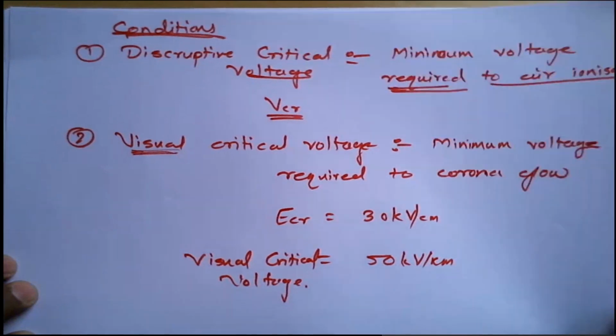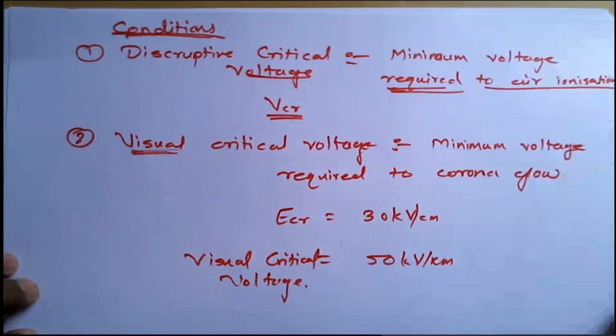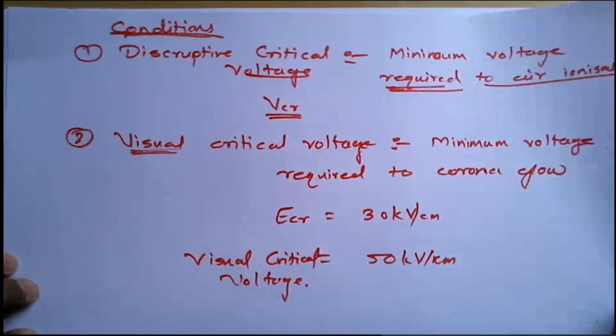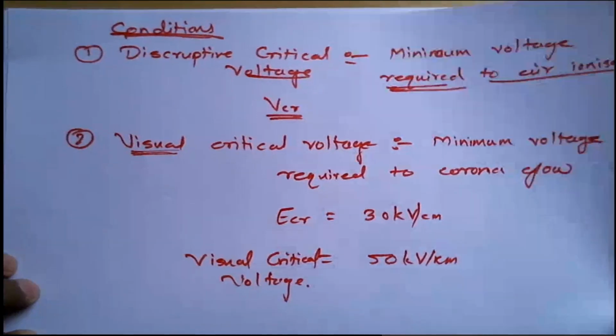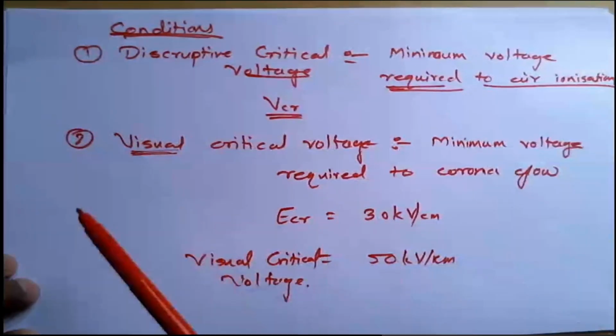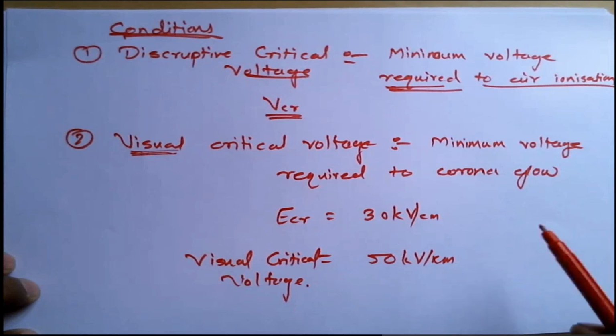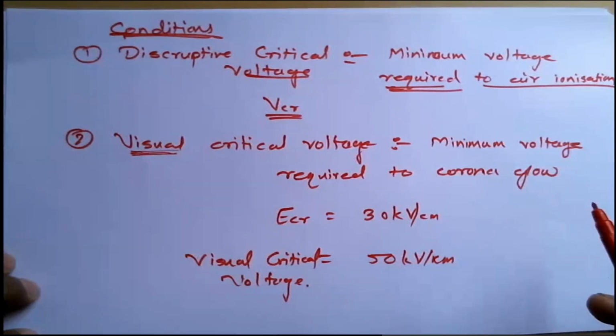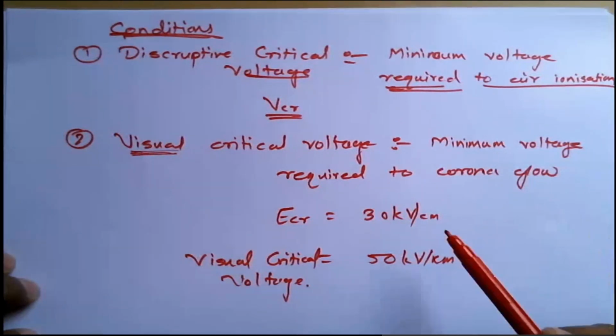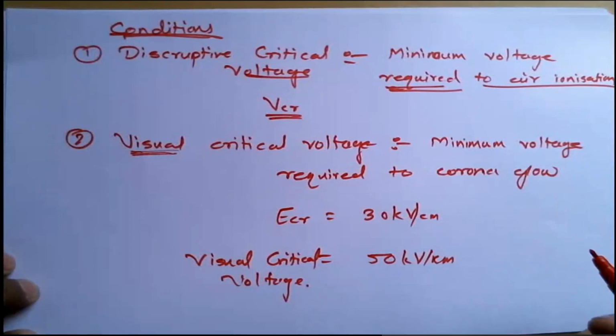Okay. So which are the factors which affect the corona, right? Corona is nothing but that whenever the air gets ionized, it becomes conductive, and the effective conduction area of that conductor increases, and generally corona occurs on the sharp edges of the insulator or conductor.